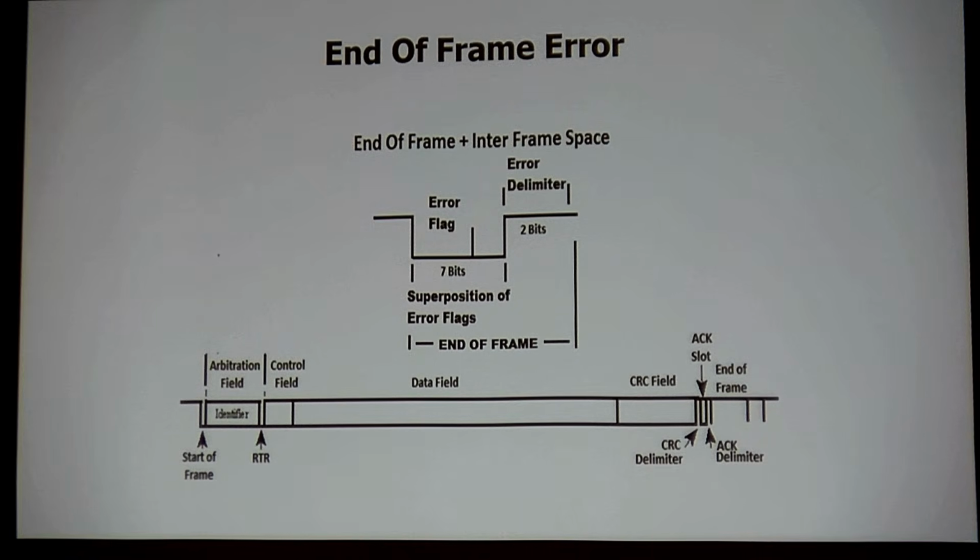And that is that there's another slot over here at the end. And this is the error delimiters. There's 2 bits. Those 2 bits can be put in by another module. So if I'm in a passive state, I'm not actively flagging, I'm passively flagging, that means that I've failed 16 times. If I get one other module that puts another bit right here, I'm kicked off of the bus and I can't talk, but I'm not kicked off. I still can listen, but I can no longer broadcast.